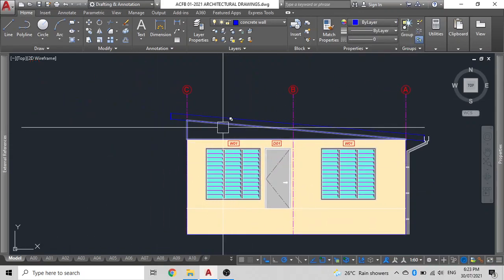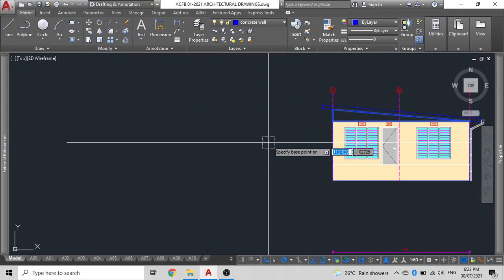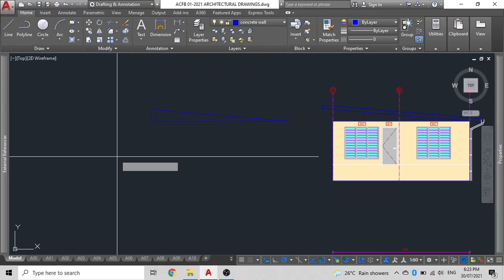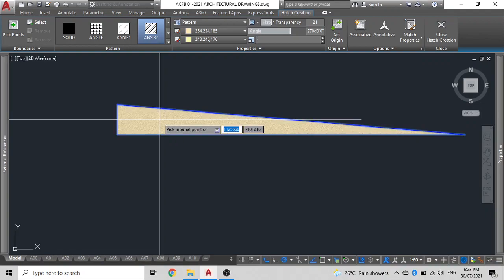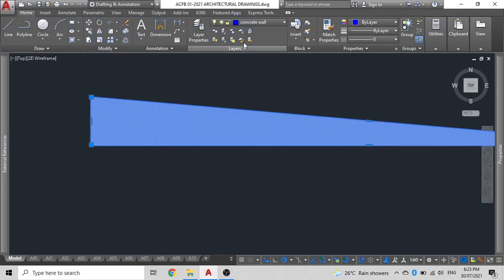Now for the top, as I said that this is a feature wall, what we can do is put an outline of weatherboard on top, so it looks neat. I'll just type H for hatch, then press enter. And then I'll select one of the lines that I think look like a weatherboard and just hatch it in there. Now here comes the fun part.